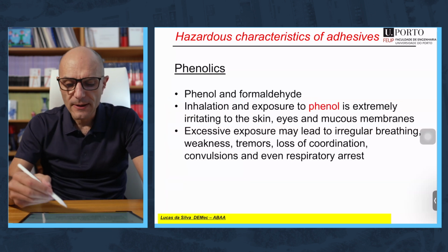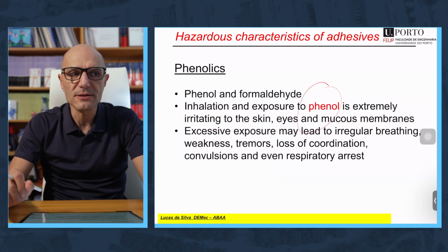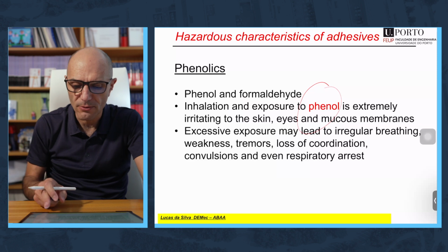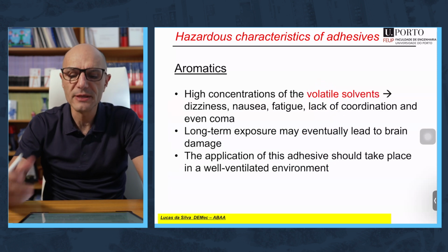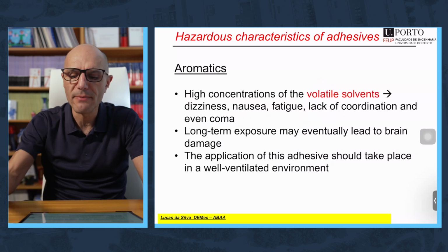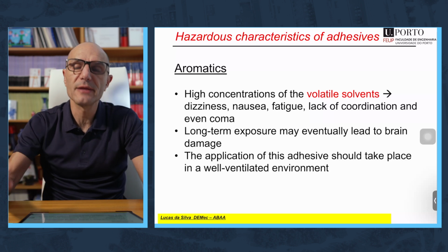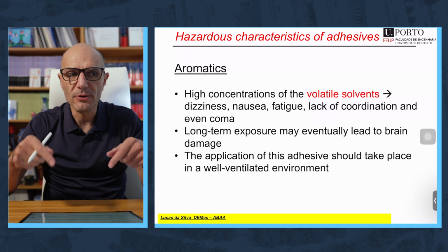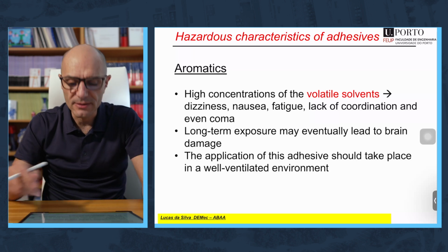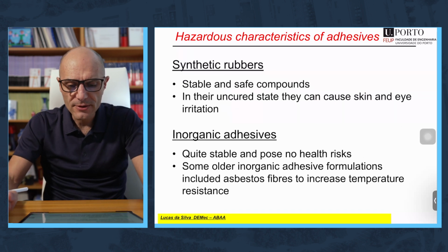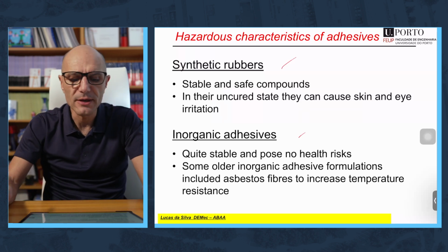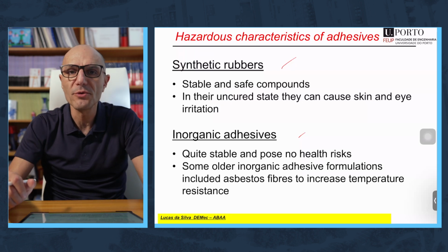Concerning the phenolics, phenol is not a very nice chemical component, so it's good to avoid inhalation exposure to this component. Concerning the aromatics like polyimide or bismaleimide, they contain a lot of volatiles to help with the spreading of the adhesive, so you should use here very well ventilated places. For the adhesives that are not structural, like the synthetic rubbers and the inorganic adhesives, there is nothing really special to talk about